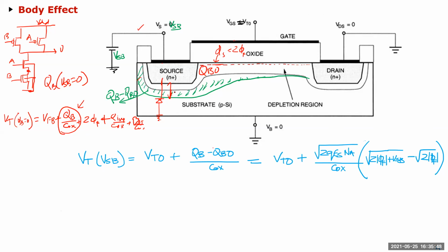It might look like you have increased the depletion charge, but this depletion charge is increased not to increase the surface potential, but just as a diode. But that also has an effect on the surface potential, which means that I need to increase this VG by this amount again, by the difference of QB minus QB0 over Cox, to get this surface potential back to 2φF. Okay.